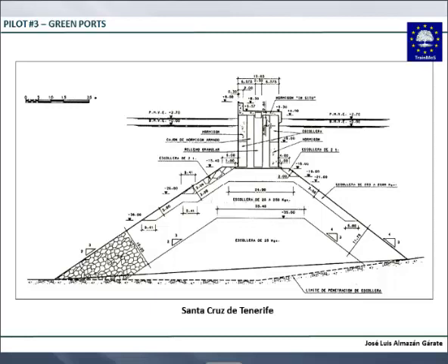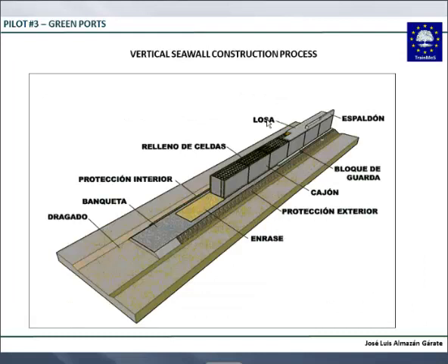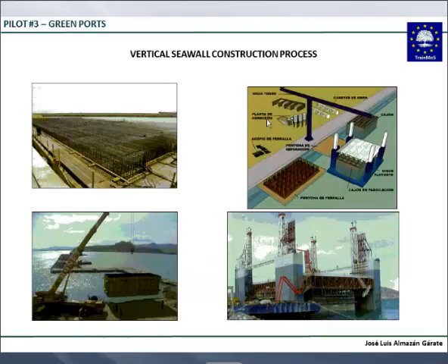Well, how do you build a thing? You build on a floating structure, and you begin to build concrete. You put a lot of iron and concrete, and then you build this caisson, and you move it, you push it with a ship or something, and it comes into position.